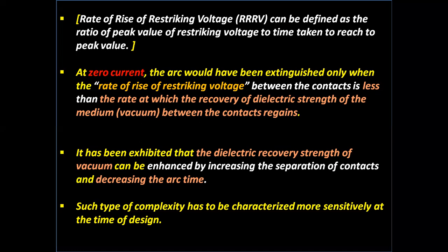It has been exhibited that the dielectric recovery strength of vacuum can be enhanced by increasing the separation of contacts and decreasing the arc time. Such complexity has to be characterized sensitively at the time of design.